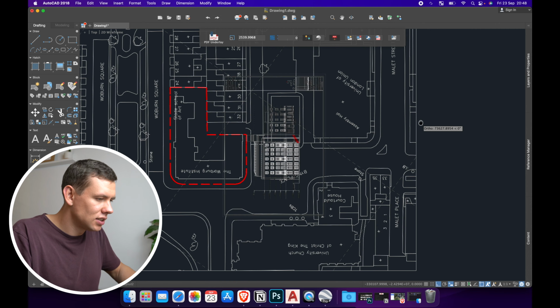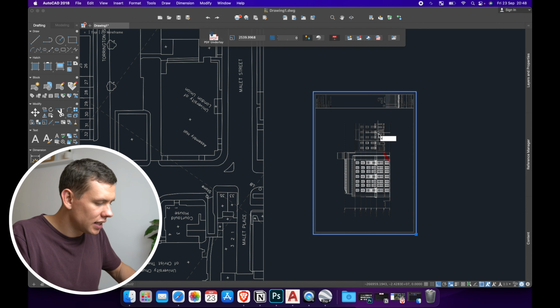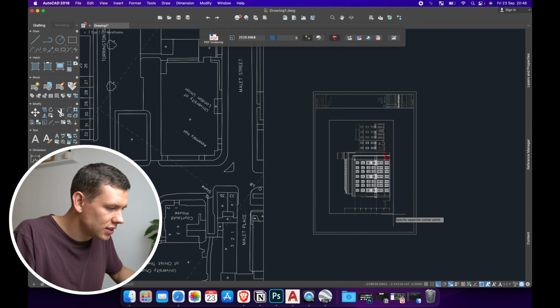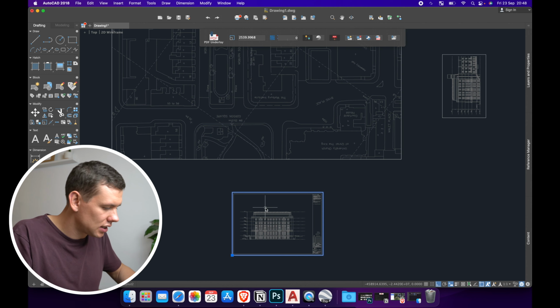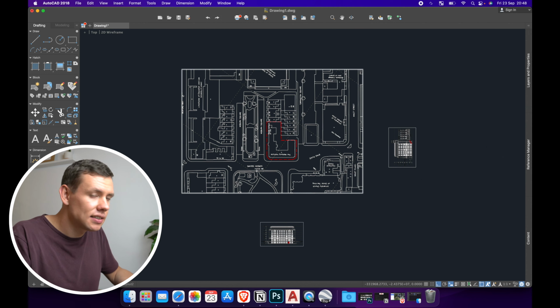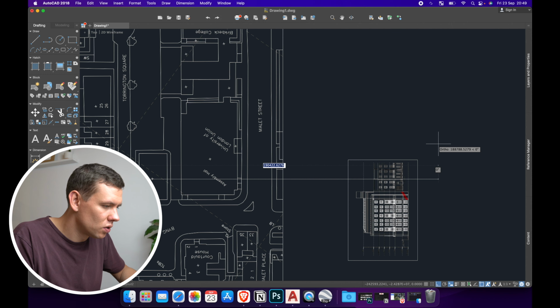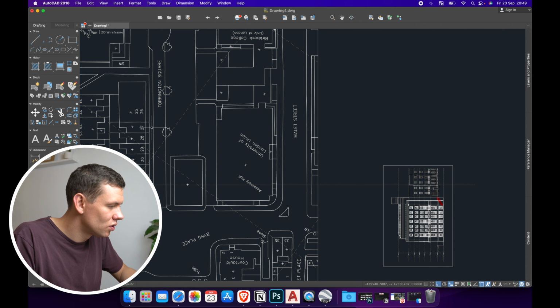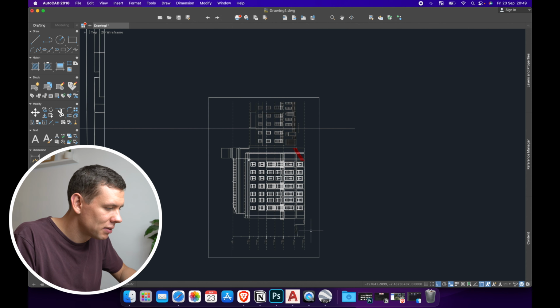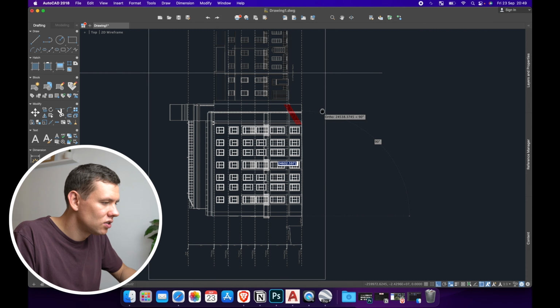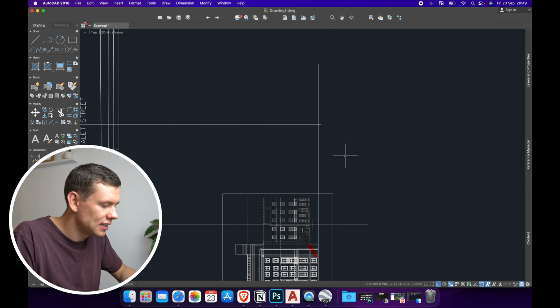That's great. We can just move it down. We can clip the view again by generating a boundary so that our workplace is kind of nice and neat. And so once this is done, it's time to start importing our images. So some of these buildings have actually been drawn up, so I think that side is going to be easier. I'm just going to draw some guiding lines, and I'm also going to draw the ground line extending out.